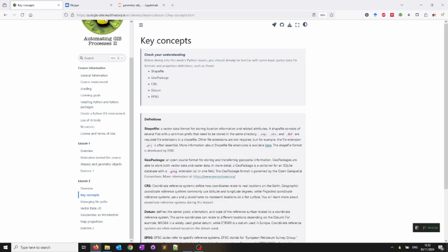When you save your vector data as a shapefile, what you get as the output is not actually a single file, but it consists of a number of files that have different extensions. So you have your geometries, your main shapefile file as a .shp file, but you also have other things such as .dbf where you store your attribute data. There can be a .prj in your shapefile's list of files where you store information about the coordinate system and the projection used.